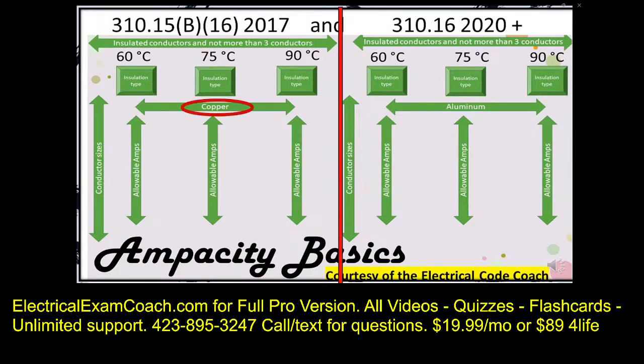On the left-hand side is going to be for copper conductors, and on the right-hand side is going to be for our aluminum and copper-clad conductors. Left-hand side copper, right-hand side aluminum. And if you'll notice, they mirror each other, but in the NEC, it's smushed all into one table. Now let's take a look at what all this information means.